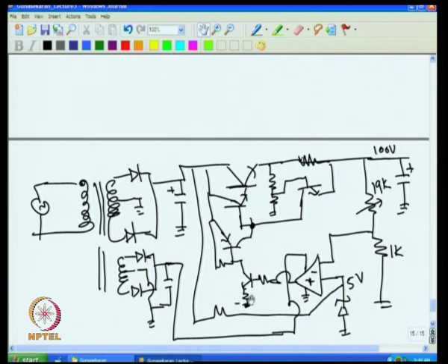So the gain is controlled tightly, because if the current here increases, that will increase the voltage enormously here, and this voltage cannot go more than 0.6. So to control the gain, we can add an emitter resistance and make it work, and it works in a controlled fashion. So this circuit also works nicely for high voltage application. In fact, this is better than the other two circuits.